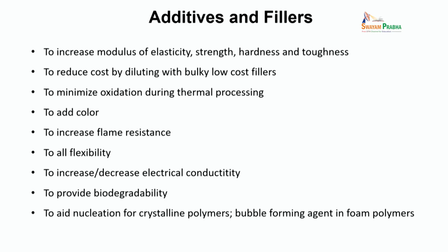Many times we also add additives or fillers to prevent oxidative degradation. When we think about a plastic product, you want the user to use it as long as possible. When you sell a plastic product, we don't sell it thinking that it should degrade after some time, in the current setting at least. So oxidation is a very common phenomenon by which polymers degrade.